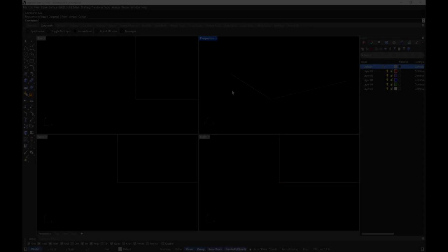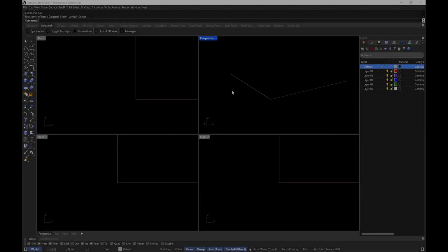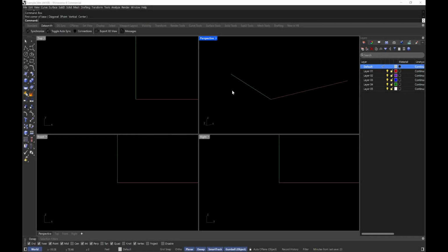So here we are in Rhino, and before I start modeling, I just want to reiterate that you can fast forward to other parts of this video if you want to just see the Twinmotion side or just the post-processing side. I have this already timestamped, so you don't have to watch the entire video if you don't want to. So let's just go ahead and start building this model. So the first command I'm going to do is the box command. So I'll type in box, and I'll just click anywhere on this space right here.